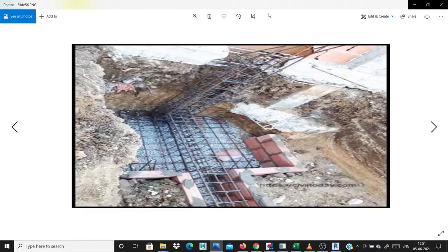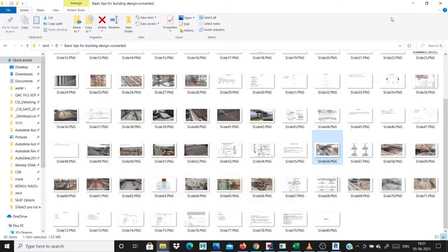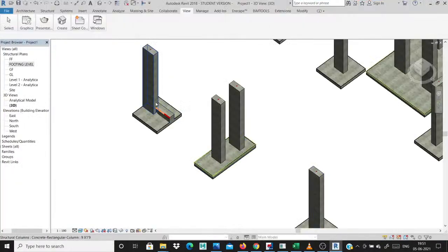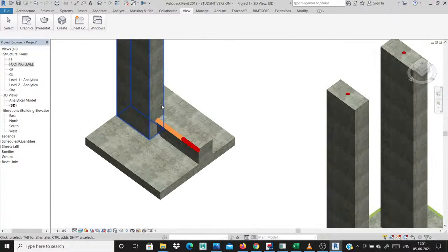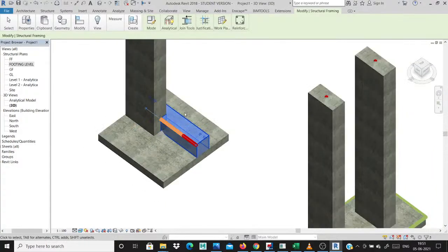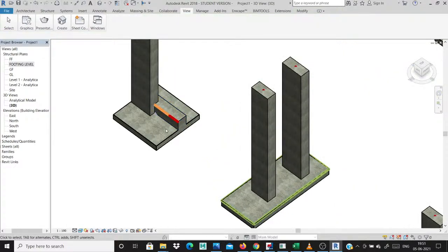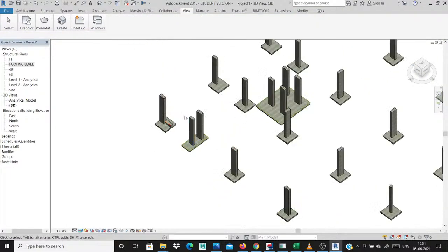This is our eccentric footings. You will create it on your site, or anybody can simply create this eccentric footing. See this, this is our corner column. This is our mat, and a beam will be provided. This beam joins this portion to other portions. The same procedure I will follow in this Revit also. I simply created this portion, then the beam. Then how to center this? Automatically a center portion will be created. This is the manner to create the eccentric footing in this beam condition also.